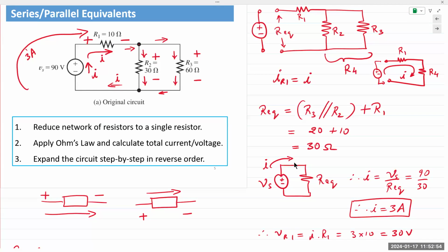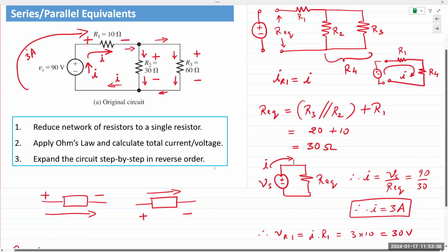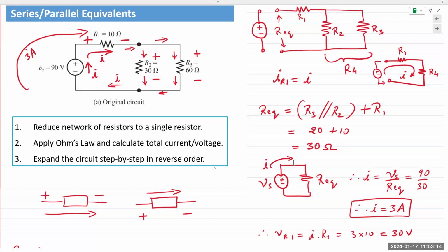But it's not as if, if 20 volts is appearing across 3 resistors, then we have 20 volts for all 3 resistors. If you remove one of the resistors from that network, then the 20 volts will change because the circuit has now changed. So any resulting voltage that appears across a parallel network of resistors is a result of all of those resistors working together. If you remove one or more resistors from that parallel network, now the network has changed, and so the voltage that appears also changes. So you have to keep that in mind.